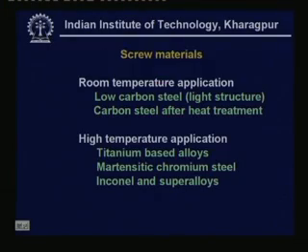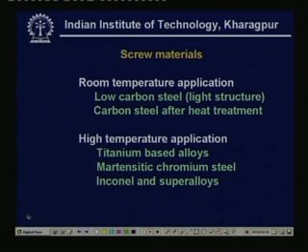Now let us come to the design. The design will definitely depend on the material selected for the fasteners. So what you are seeing is a list of the screw materials. Now the screw materials will be chosen depending on the temperature of the applications. For room temperature applications, the materials are low carbon steel, this is for the light structure, and maybe medium carbon steel, but it must be heat treated.